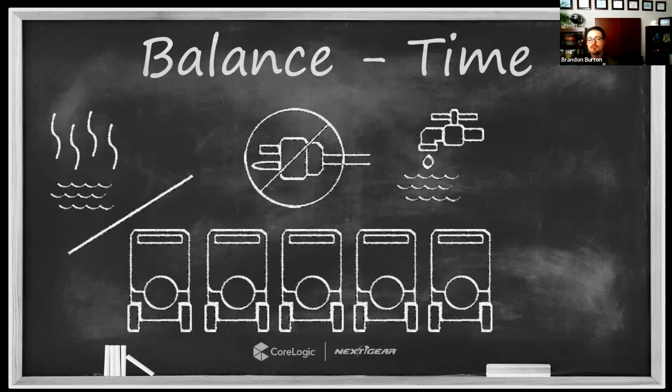Let's say that the problem is that we have additional moisture in the environment that hasn't been addressed. Let's say there's a water source that has not been identified, and there is still bulk water in that environment. And the reason humidity is increasing over time is because I'm not properly compensating for that bulk water. It wasn't extracted, that source wasn't identified, et cetera. If I throw additional dehumidifiers at the problem, I'm just going to mask that issue, right? I'm curing the symptom, I'm not curing the problem, right?